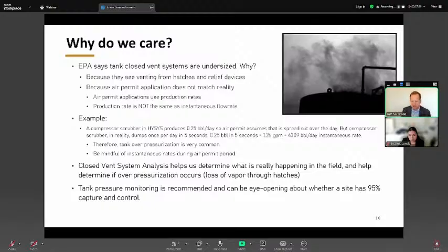So in situations like this, you find that overpressurization becomes very common. The EPA recognizes this because EPA established all of this in Colorado in the DJ Basin, north of Denver, where they have plunger lift. Plunger lift wells are where you get your production over a plunger run, and you might only have 10 plunger runs a day, such that all your fluids are condensed into 10 five-minute plunger runs. And so you get that exact same phenomenon. So EPA, through working in Colorado, established that they knew these wells could be surging, and so they highly scrutinize how we approach production.